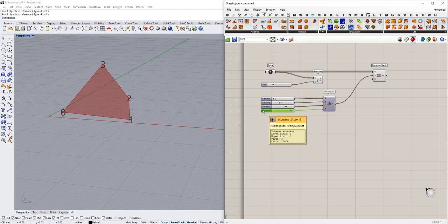There are ways of taking a mesh with non-planar faces and trying to optimize it so everything becomes planar, and that's pretty useful. Say if you're doing a facade system where you had a lot of non-planar faces and you want to optimize it so that you can make things out of, say, flat stock like sheet metal or wood or something like that. But usually when you're making them on complex geometry, they will not be a planar mesh.